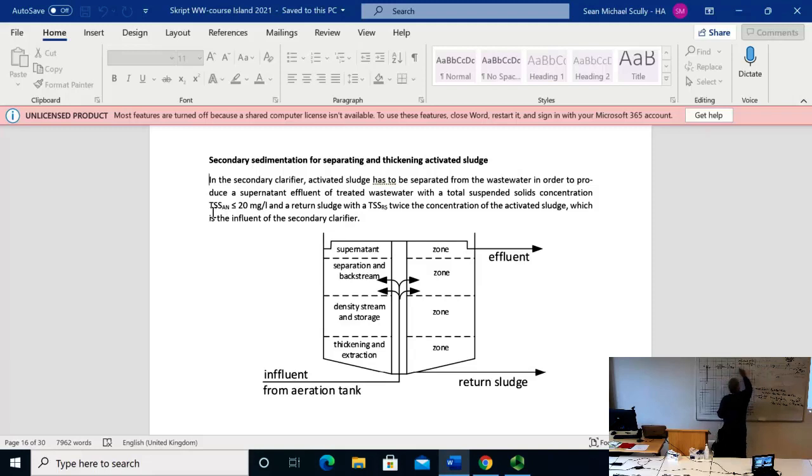Now the time of thickening in a standard plant is 2 hours. It might vary between 1 and 2 hours, no? But normally you take 2 hours. You just take less time if you do not have good denitrification. If you do have only nitrification, you cannot store the sludge so long in here because then you get an unwilling denitrification, and then the sludge is going to float. Due to that, you have to solve that.